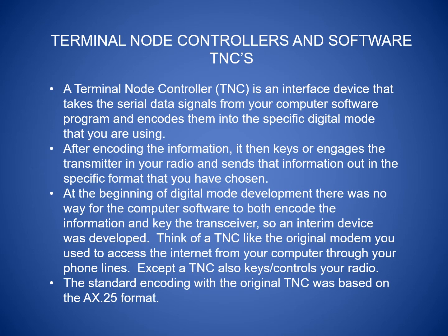A terminal node controller is a device that's external to your computer and your radio, and it takes serial information from your computer software and it codes that into a specific digital mode that you are using. So after encoding the information, that TNC then engages or transmits push to talk on your radio and sends that information out in the specific format that you have chosen.